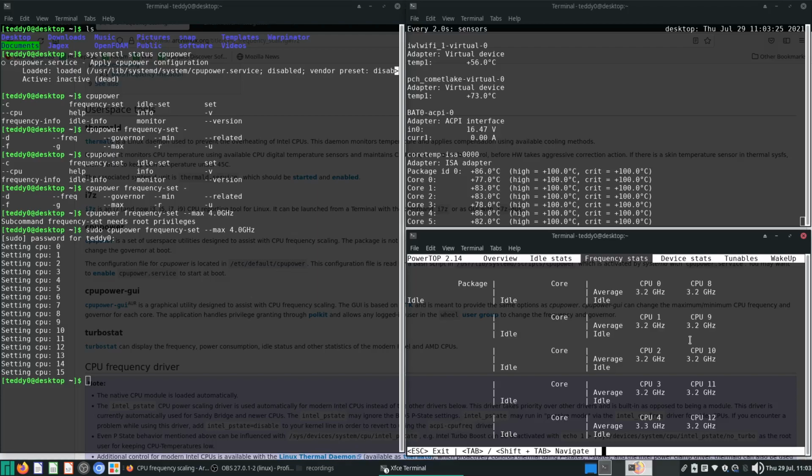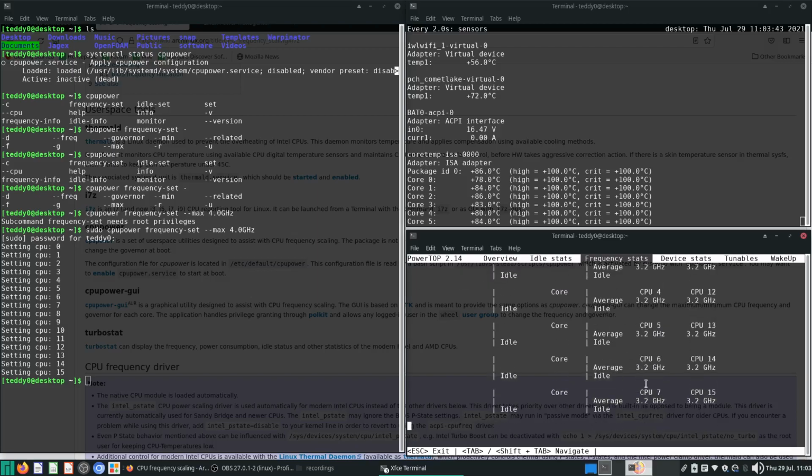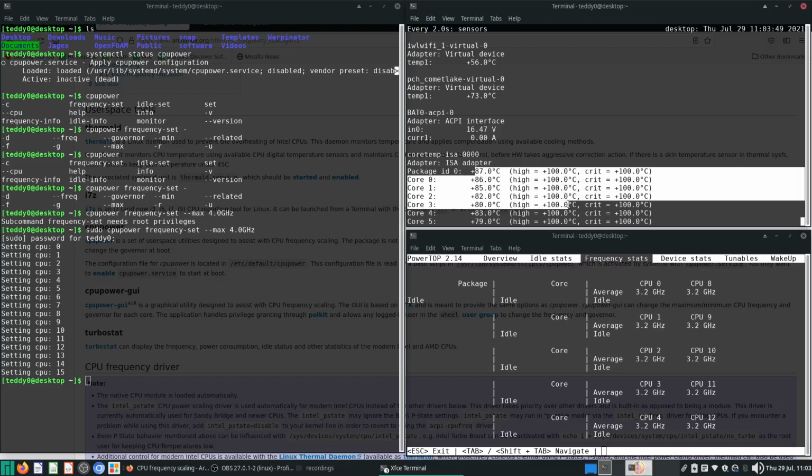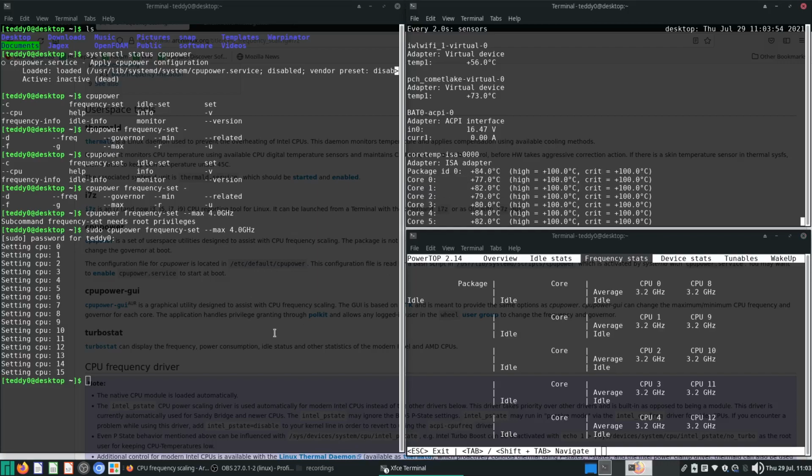Now, of course, the fans and everything are adjusting their rates so that things don't run so quickly, so as to manage the temperature. Yeah, around 90 degrees C is where you start to have maybe some throttling, where the BIOS might start to power down the CPU. Now, even then, I don't want my CPU to run at this sort of temperatures. It's way too much. Okay, so it's going at 85. It's going down.